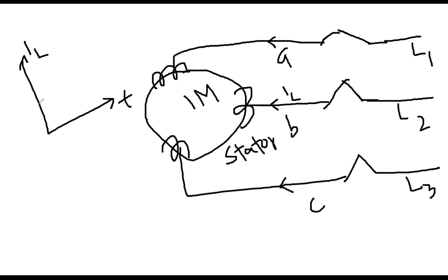For example, if this is its rated amount, it should be the current magnitude from here. But because of suddenly energizing the 3 lines, the current value might go very high, and then gradually it will settle down. So this is called the inrush current or initial transient current. That will happen if you do it in that manner.